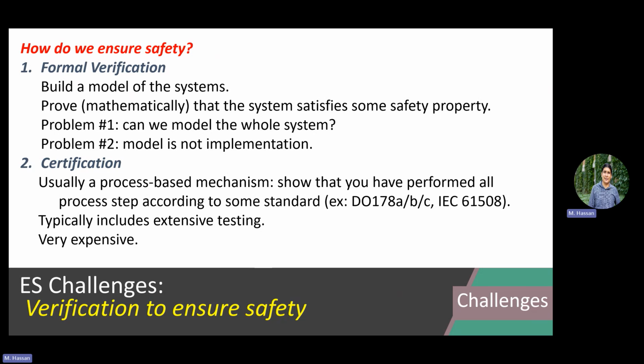Why is formal verification sometimes, especially for the highest critical levels, the way out? Because through formal verification, you don't need to redo testing under all scenarios, right? Once I formally verify, I'm good, no matter what else is outside; you can ignore the environment completely, right? What is the problem with formal verification? It can work for a simple system, but for a system as complex as a self-driving car on the road with all the uncertainties, how can I really formally verify all the hardware and all the sensors and cameras in that car? It's almost impossible, right?